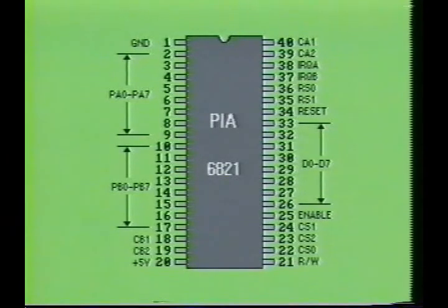The MC6821 is a typical input-output chip designed by Motorola to operate with the 6800 family of MPUs. This IC may be found operating with the 6800 8-bit computer or with the 68000 16-bit computer. The 6821 is a peripheral interface adapter, or PIA for short, which is constructed using NMOS technology. Data bus lines D0 through D7 allow the microprocessing unit to write data to or read data from the 6821 as if it were a memory location.